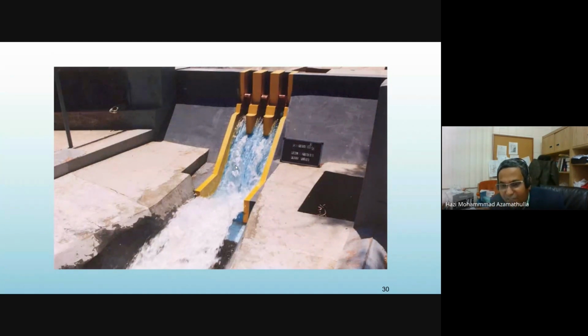You are all aware of cavitation, (P minus PV) by rho V square by 2, those who teach fluid mechanics. Very very important. Another thing, this water level should not be more than your training walls. Also you can see the rooster tail. This is called rooster tail, two roosters, that is the beauty. The jet hits and sprays, so the energy is dissipated in air. Okay, next please.